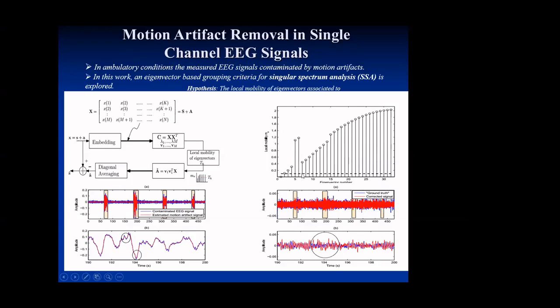So how to find that? For that we have fixed a threshold. How is this threshold decided? We have chosen this threshold as 0.1. All the signal components above this 0.1 we call EEG signals. Below this, only this component is there, which is called the motion artifact. The threshold is decided as follows: normally the highest frequency of the motion artifact is 4 Hz. So we have taken a 4 Hz sinusoidal signal and estimated the amplitudes. From that we fixed this threshold as 0.1 millivolt.